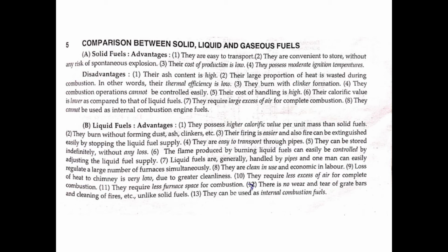The solid fuel has some disadvantages. Their ash content is high. A large proportion of heat is wasted during combustion. They burn with clinker formation. The combustion operations cannot be controlled easily, their cost of handling is high, and the calorific value is lower as compared to liquid or gaseous fuels. They require a large excess of air for complete combustion, and they cannot be used as fuel for internal combustion engines. Okay,